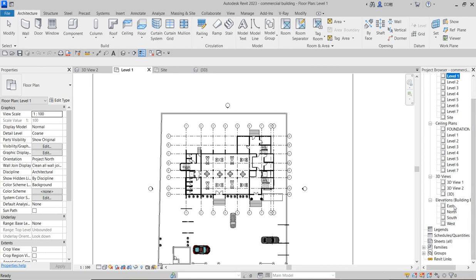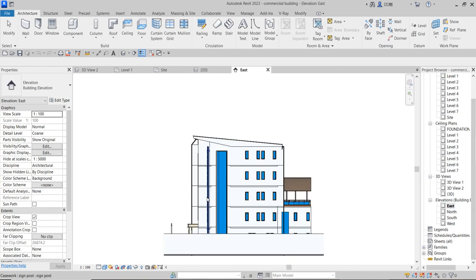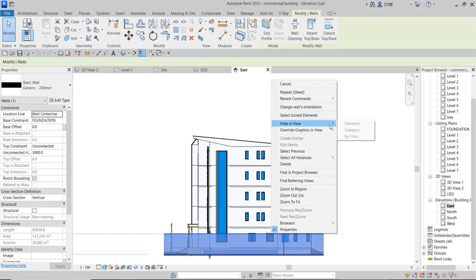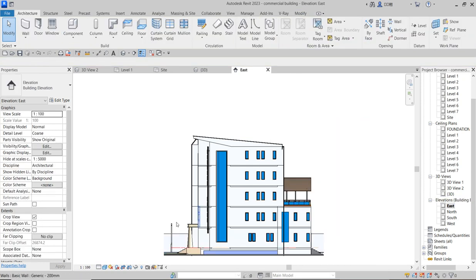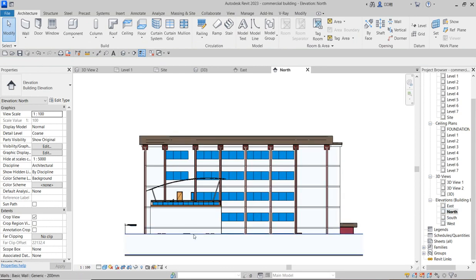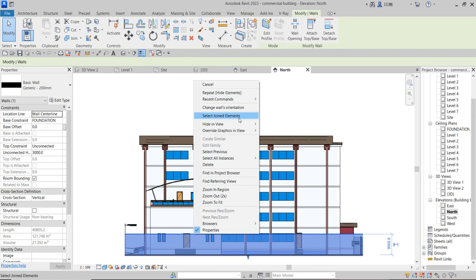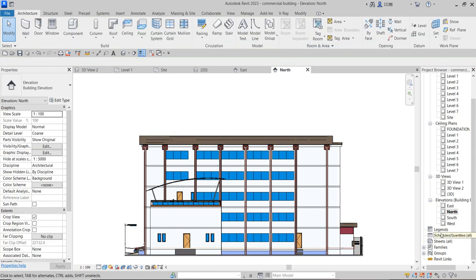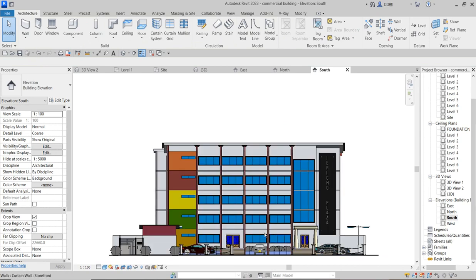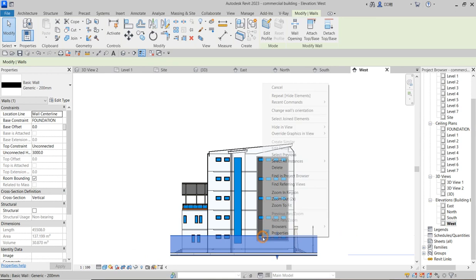So what we do? Check all the elevations, whether they are in right parts, in right proportion. Like this, now you remove or hide, you just hide it. You don't remove it because they are still functions. So hide this, that is fence that we created. So anywhere you see there's one thing or the other that is obstructing the whole entire view, what you need to do is to hide. Click on hide. So this is how you go around. So this one have no obstruction for now. So capture the whole, including the gatehouse and every other part. So you do the same thing here too.